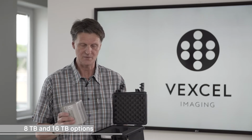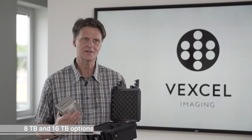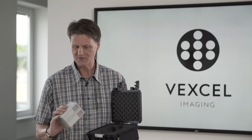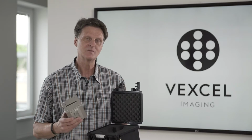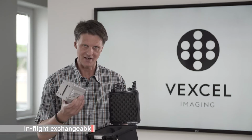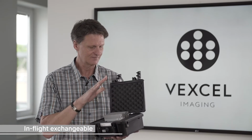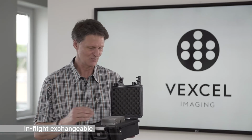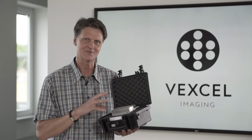That's quite impressive in volume, but on the other side, the UltraCam Osprey collects so much data in such a short time that if you are on a performance flight with a fast plane, you can easily fill up at least one, maybe even two of these 16 terabyte data units per day. So that's why they are also in-flight exchangeable, and they come in this nice case, and it's highly recommended to have at least one spare during your flight, as you will be surprised how quickly the UltraCam Osprey 4.1 fills up these nice drives.